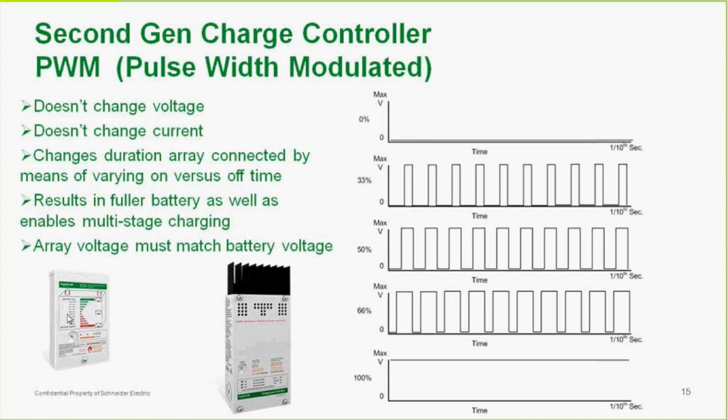You can also use it as a load controller. So it has 3 sets of terminals: battery terminal, array terminal, and a load terminal. So you can run a 12-volt load like a light. For instance, if you use it as a bus stop lighting controller, it would charge the batteries, maintain the batteries full, or do the best it can, depending on the array. And then when it measured the array voltage dropped to below 3 volts, it would assume that it's nighttime and then turn on the lights, and then protect the batteries from over discharging by turning off the lights if the batteries go too low.